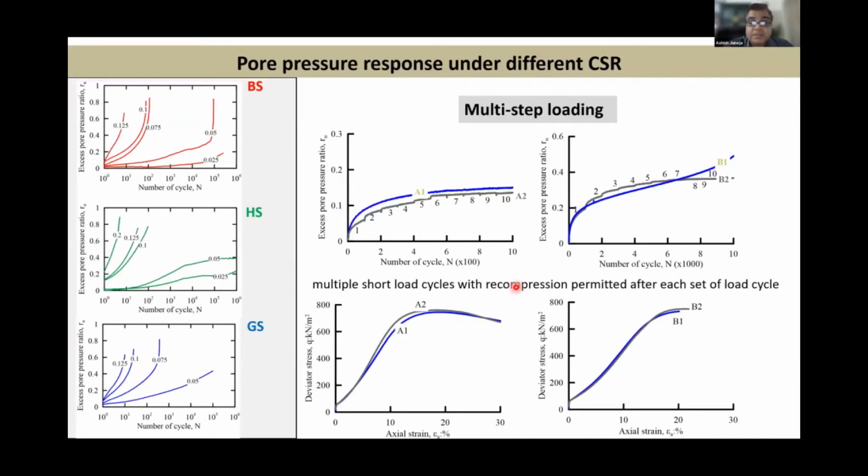It's typical standard. One additional thing we noticed was the excess pore pressure ratio when we plot it against the number of cycles. If I take one single test of something like 1,000 cycles or maybe 10,000 cycles, a blue line shows a single test going straight through, and the grayish line shows a similar soil sample, but this time it undergoes hundreds of cycles. The right side is thousands of cycles.